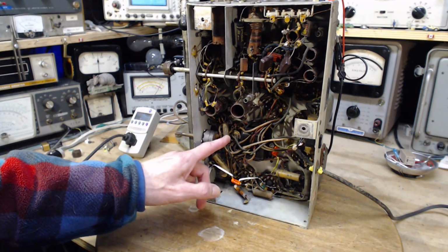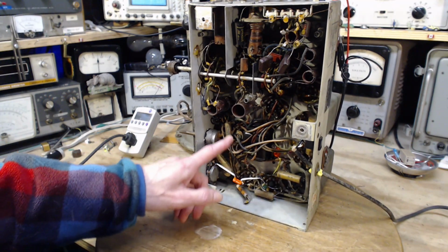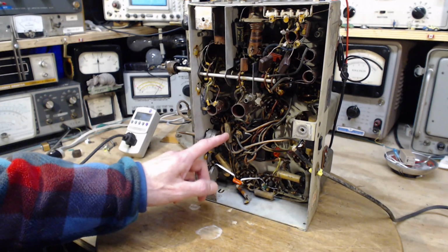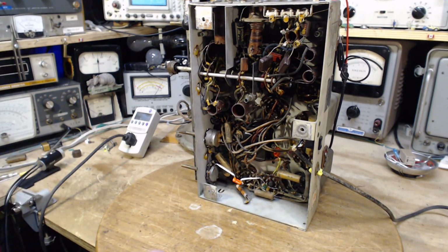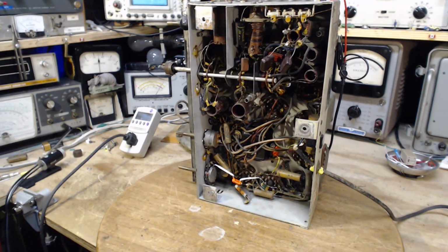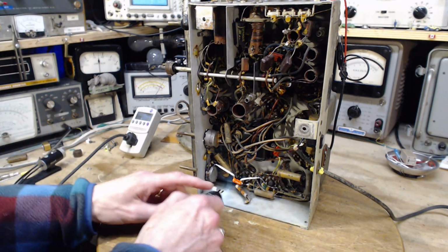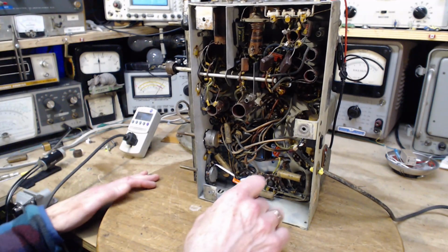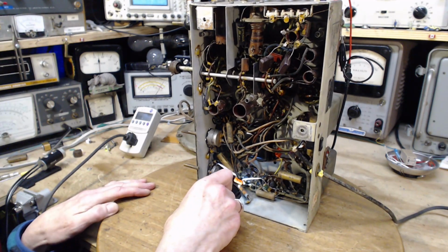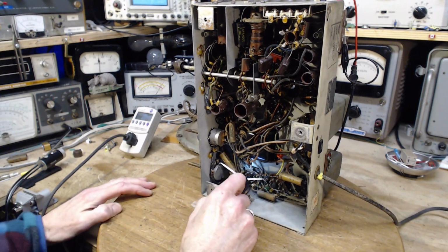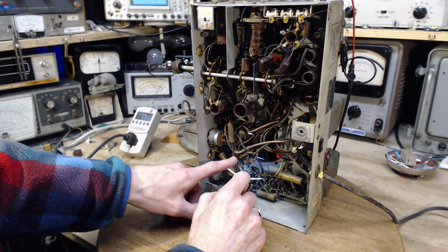So there's a capacitor from the plate going to the chassis. I don't think that's what's on the schematic. Let's just double check everything here, so I'll get my super weak flashlight. I'm looking for the key on the tube. I'm counting 1, 2, 3. There can be no question. This is connected to pin 3.